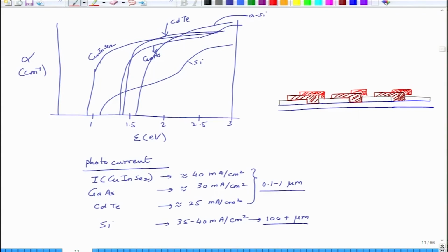You have to isolate them though. So, you make a front contact, you make a back contact. You can't make them touch each other. So, hang on. And then you put a top contact, and so on and so forth. And then of course you make a top glass cover. So, you have a back contact, you have a front contact, and you have the semiconductor in between.